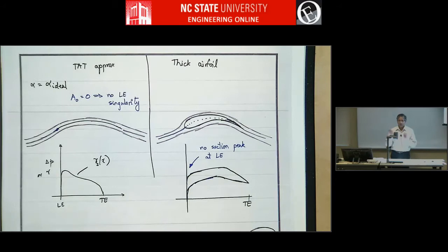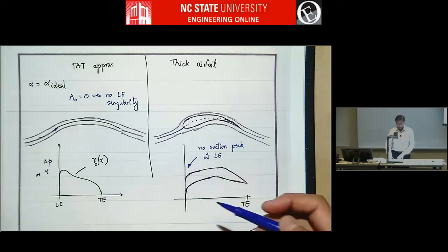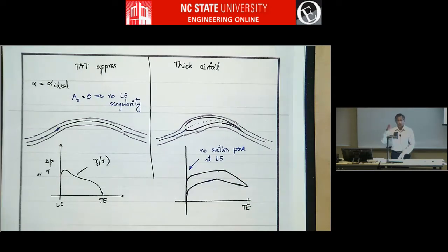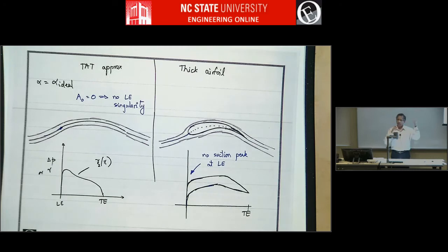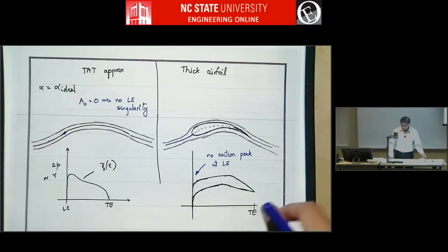The leading edge is sort of meeting the flow in a nice way, right? So this is like a sweet spot in angle of attack. So if you have a laminar flow airfoil, this will most likely be at the center of the drag bucket, because neither the lower surface nor the upper surface has a suction peak. So this is at alpha ideal.